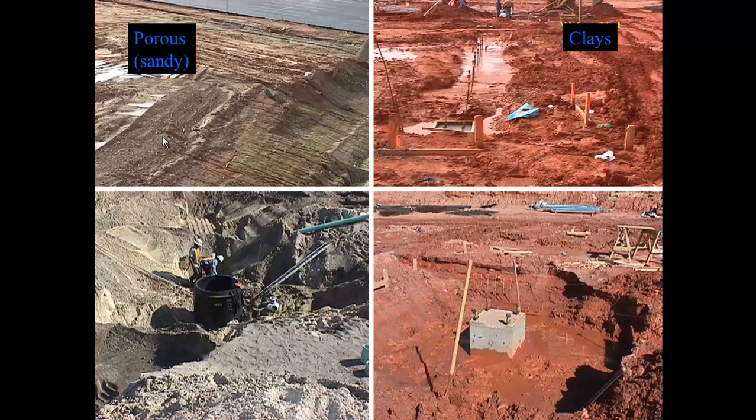We see some porous sandy material. Over here we see some clays, and there's that sloppiness with the water in there, and it just becomes a mired pit. And same down here. Here's some sands. One thing about sand, it does have good drainage, but it also is something that is tough to maintain the shape of as far as digging holes. We've had contractors, workers, that get buried by this stuff sliding out.